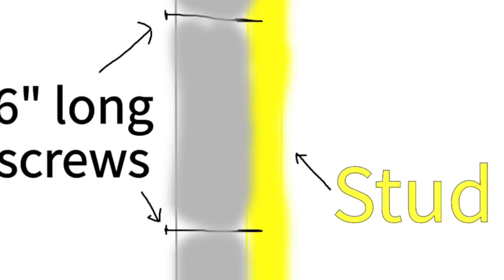When you're screwing the screws through the battens and trying to find studs, it can be a bit of a challenge. So it's really just trial and error. Eventually you'll figure out where the studs are just based on the sheathing of the house, and you can tell that, hey, this is an edge of a sheathing, this is an edge of a sheathing. Clearly there's a stud underneath these 2 edges where they were nailed in, and you'll be able to figure out where to actually screw the batten into the stud of the house. Also, you can go around to the inside of the house and double check your work to make sure that the screws didn't miss the stud and just go directly into the sheathing of the house. It's really important that each screw goes directly into the framing of the house.